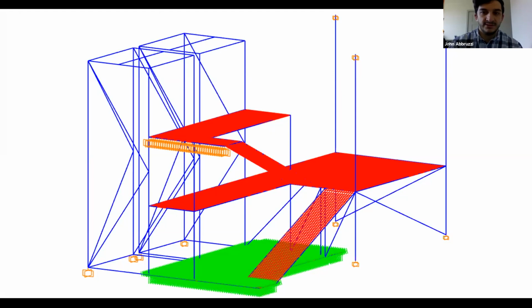These springs were applied to the basement floor as the foundation is assumed to be resting on a structural soil. The springs also serve as a restraint for the front part of the elevator shaft.